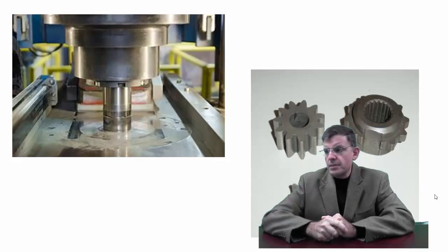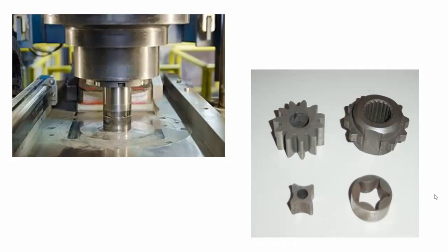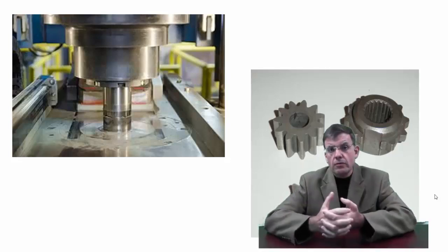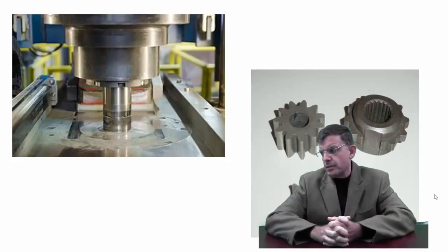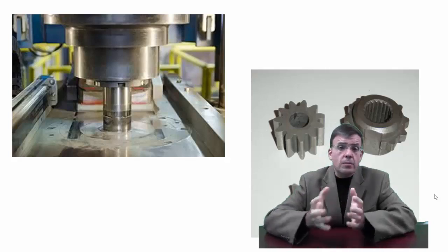Okay, this is powder metallurgy here, so it's not nearly as common. Again, in the prototyping realm, these tend to fit only particular geometries. It's hard to tell from the picture, but this consists primarily of taking metal powder, compressing it, perhaps adding a binder to it, and then sintering it. Sintering is the word that we use for letting that powder fuse into a fully formed or a fully solid part. And again, you see some examples there. This has a tremendous application in, for example, automotive parts.